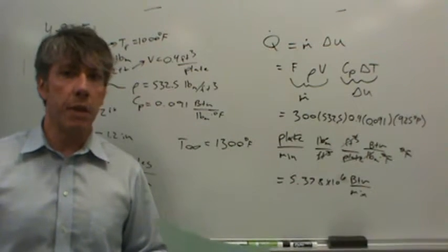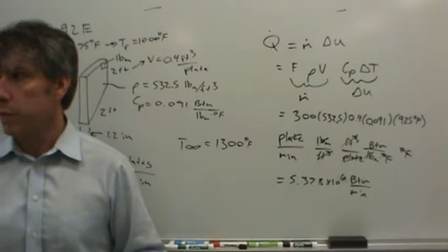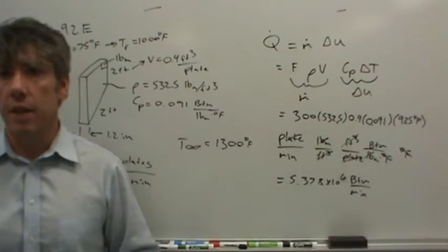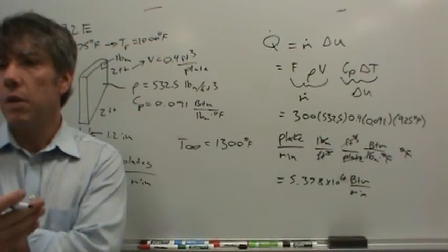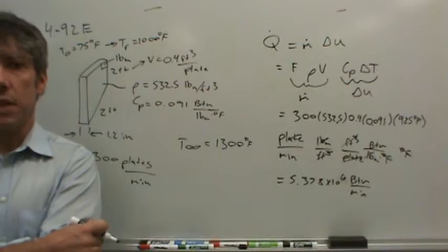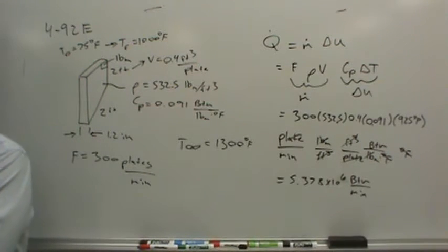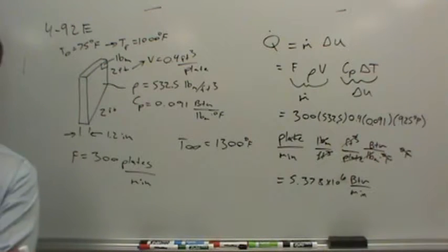My electric bill runs anywhere from about $100 to $200 a month, depending on how much I run my AC. So for that, it turns out electricity costs about, very roughly, 10 cents a kilowatt hour. It's actually a little higher than that now, but that's good enough for our back of the envelope calculation. So let's say I pay $150 for electricity for my house. At 10 cents a kilowatt hour, that means I bought 1,500 kilowatt hours. Does that make sense? So 1,500 kilowatt hours of energy.